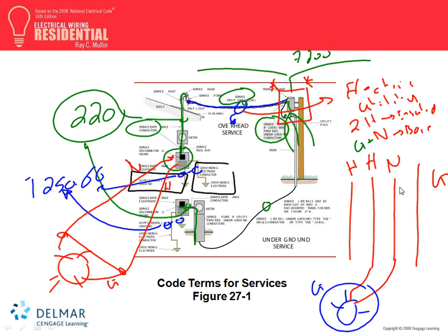And I have a short circuit. I have a hot going to the ground. And here's my grounding conductor right in here. See, I have a short circuit, right? This is a short circuit right here. I have my hot, my neutral, so the light is up and running. I have a ground fault right here. So where is the ground fault current going to go? From here, it's not going to go through the neutral. It's going to go through the frame all the way back to here. And then what? Then what?